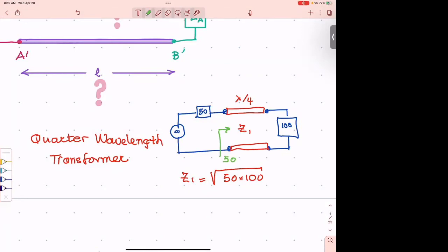When the internal impedance, Z sub S, becomes real, the only time you get maximum real power going from here to inside here is if this input impedance at this point is 50 ohms. That's the only time. So we have to make this point 50 ohms.